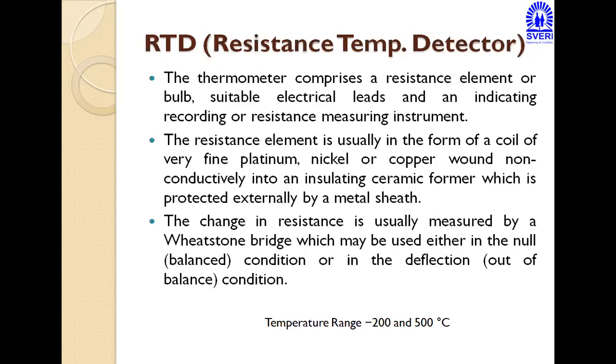The resistance element is usually in the form of a coil of very fine platinum, nickel or copper, wound non-inductively into an insulating ceramic former, which is protected externally by a metal shell.